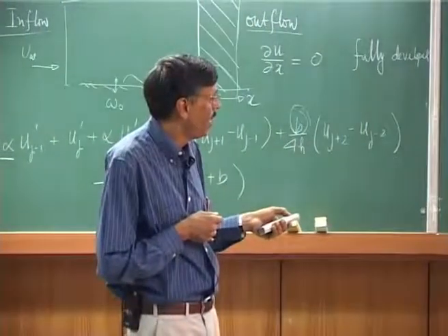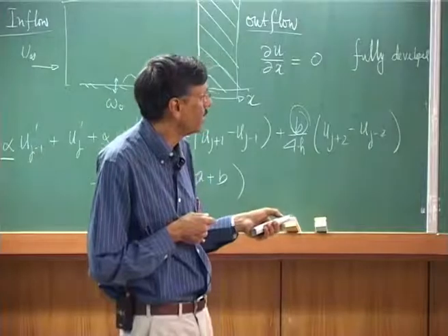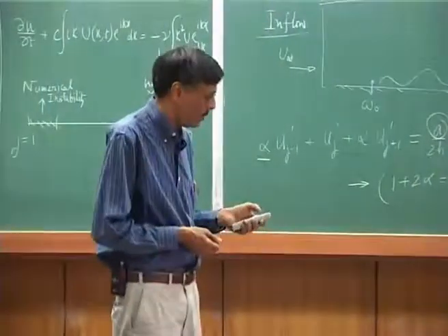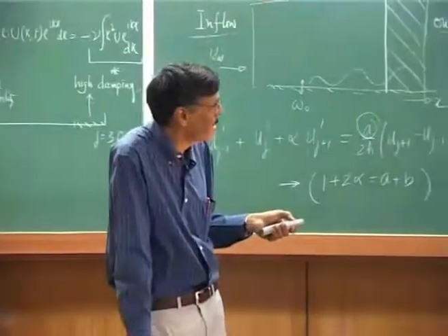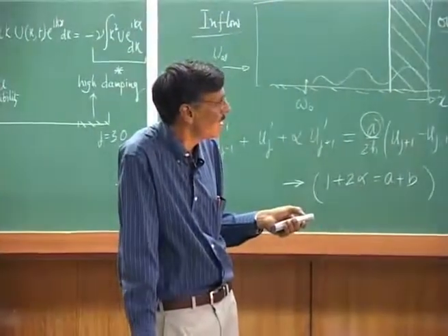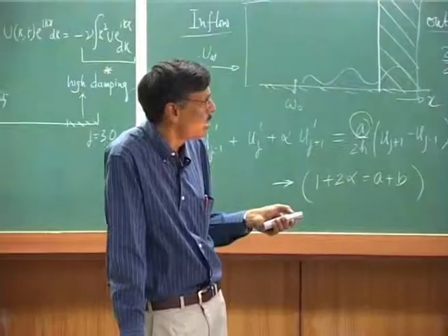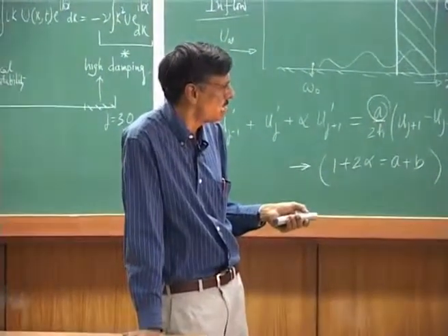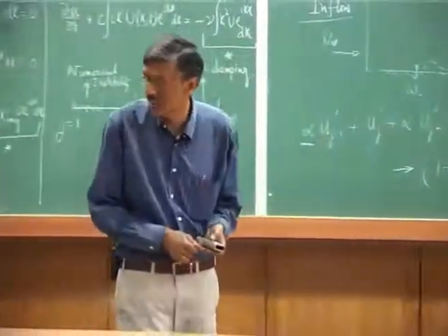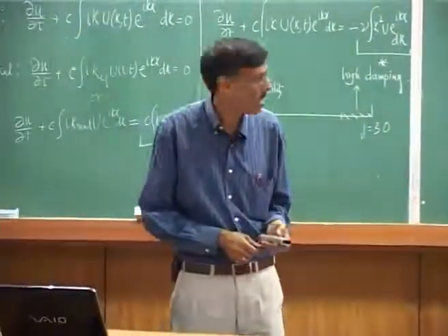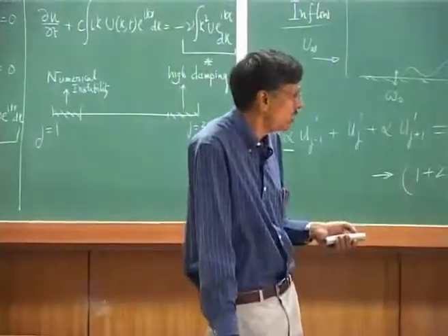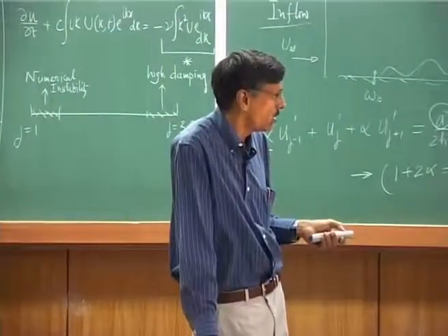Basically, we are finding the mean square departure of the error, obtained at, let us say, the jth node. So, this is a local property. We could sum such departures across all the nodes in a domain and construct a global objective function, which is the sum of all this, and this is what it would look like.